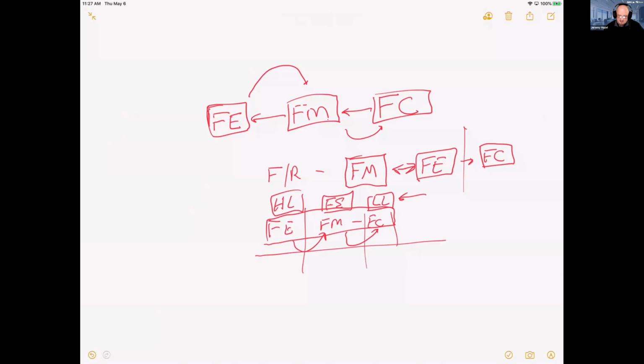And if you are at a certain level of integration, say this is the disc brake system, when you drop levels, the failure mode becomes the failure effect, the failure cause becomes your focus element, and then you are able to find the new failure causes for that failure mode of the focus element.